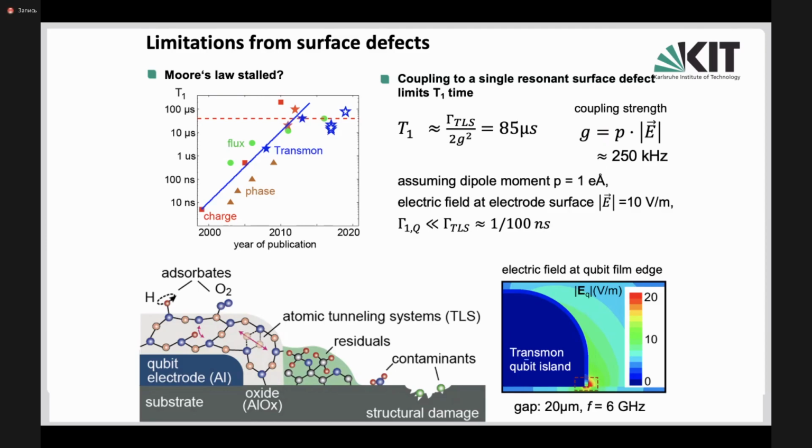And if this dipole is sitting in the tunnel junction, which has separation between superconducting electrodes of the order of, let's say, 10 to 20 angstroms, then this very tiny charge will produce an electric field variation in the capacitor of the junction, which will couple to the electric field induced by the plasma oscillations of the junction, which, as you know, are the oscillations characterizing the states of transmons, for example, or charge qubits. And similarly, there will possibly also be magnetic interaction, but magnetic types of defects have been reported only a few times and not really observed systematically until now.